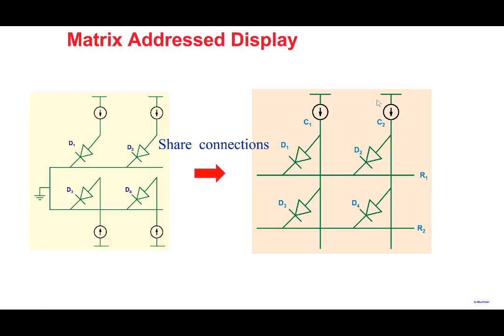But then, as we just said, if you immediately start doing it 1000 cross 1000, you will see that the number of external terminals here would be 1000 plus 1000, 2000. While here, 1000 across 1000 will become 1,000,000 terminals, right? So 1,000,000 versus 2000. So this is manageable. When you have 2,000 connections coming from here, 1,000 connections coming from here, we can manage those number of connections and those number of wires. But 1,000,000 connections, a million wires, that is unmanageable, right?